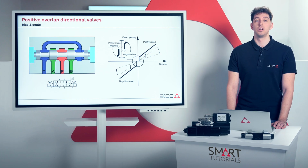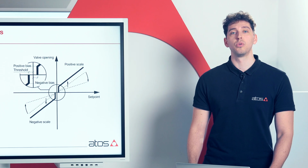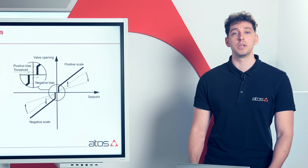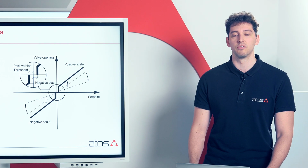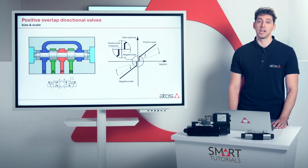Instead, the scale function limits the maximum solenoid current or the valve spool position, controlling how far the spool can move at the full set point. This is useful if you want to limit the actuator speed or you are using an oversized valve and you want to reduce the maximum flow rate. Also for the scale, for bi-solenoid valves, you have to set two different values for positive and negative regulation.